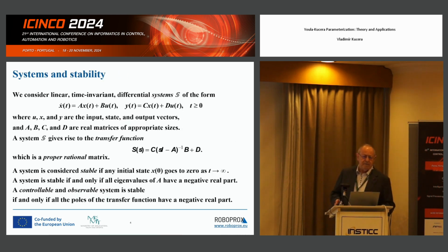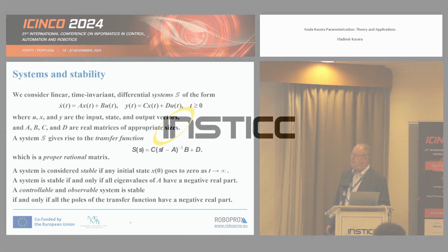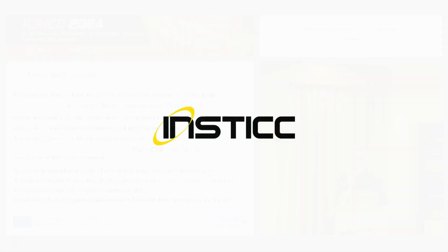We consider systems that are linear, time invariant, described by differential equations in state space form, where U is the input, X is the state, Y is the output, A, B, C, D are matrices of appropriate sizes, and the system gives rise to the transfer function, as shown here, which is a proper rational matrix.